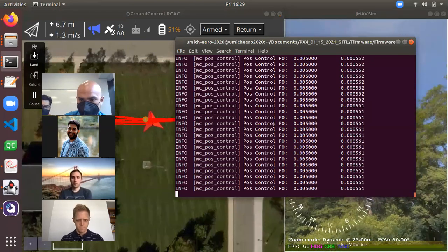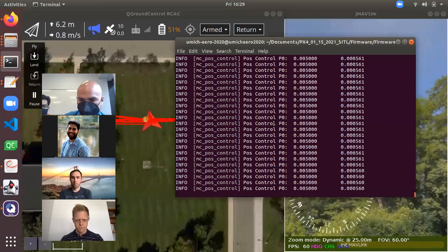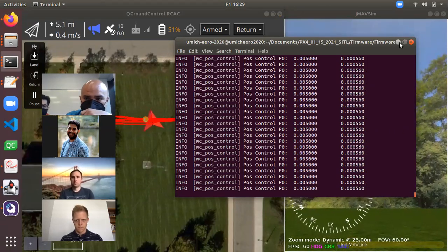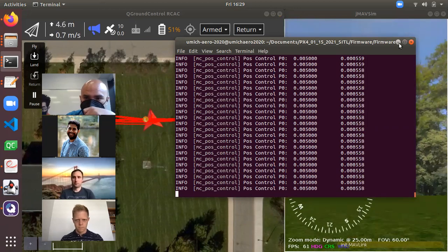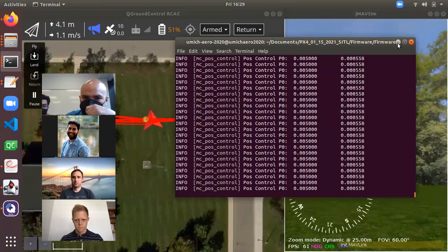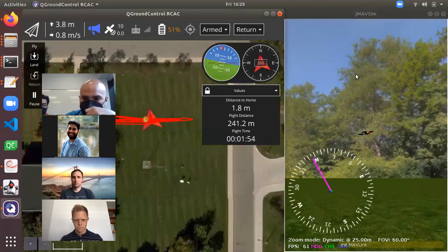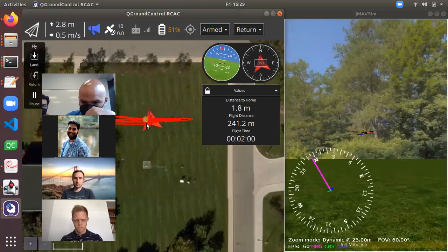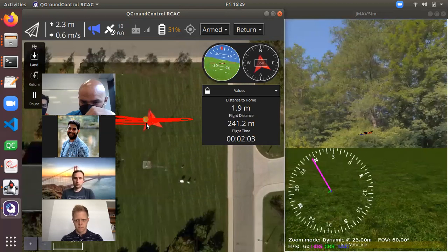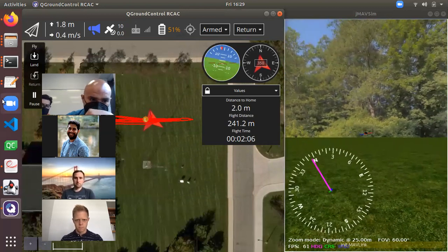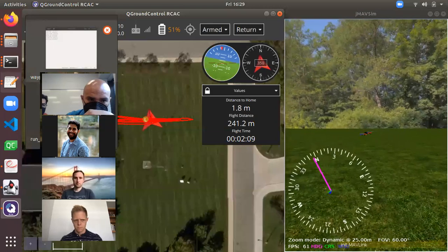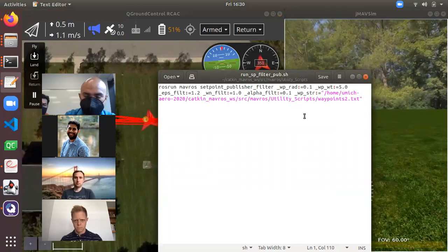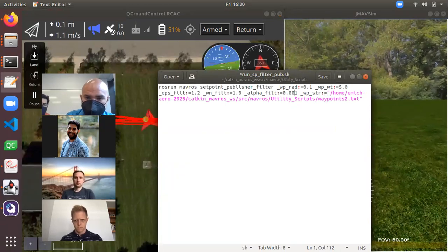Yeah, position controller P gain is 0.5. That's not changing. I don't know what the second variable is. Huh, interesting. I don't think RCAC is on in this case. So this was the issue I saw earlier also with the MAVLink setpoint publishing. It's probably publishing these setpoints way too fast and it gives a very aggressive command. That's why it's producing like a 20 degrees tilt, because the reference is too high. So maybe make it slower. Yes, your setpoint publishing, make it slower. Yeah, I was thinking about that.